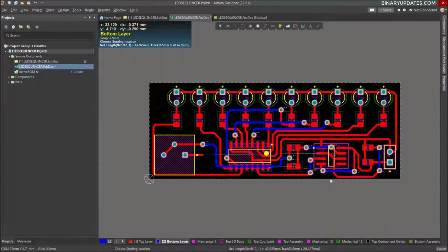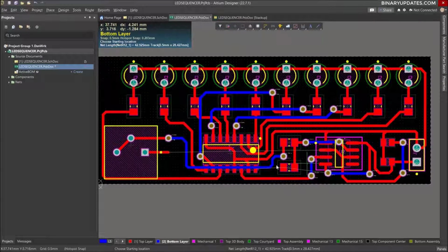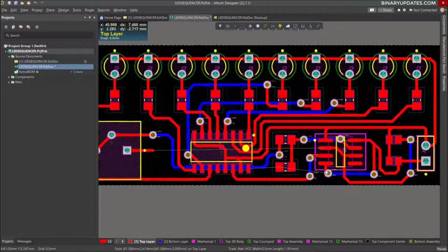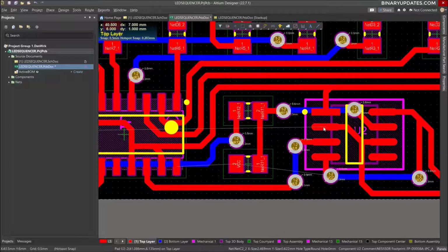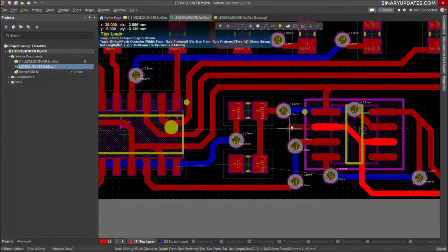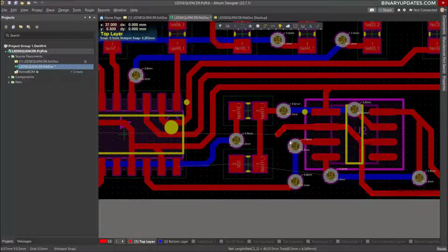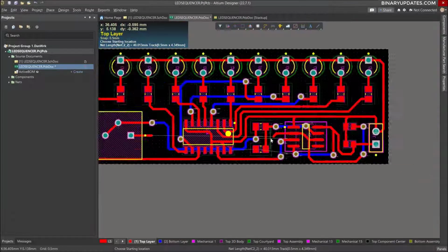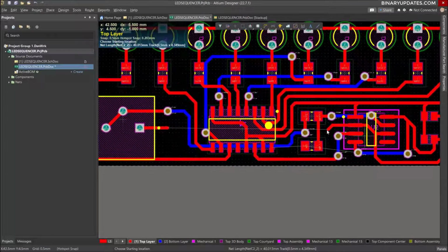I think it's done. Press escape, select the top layer. Now I have these connections. Looks the complex one. I need vias again for this layer, this pin. So I take this and right click here, and then I have this two connections to be made.